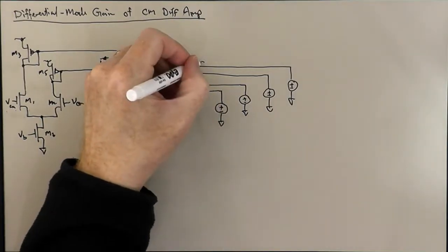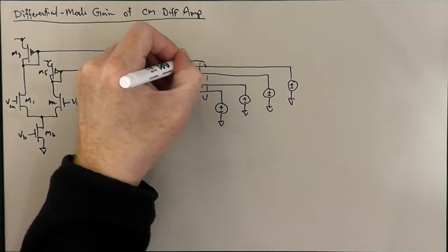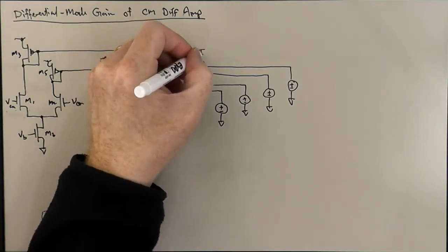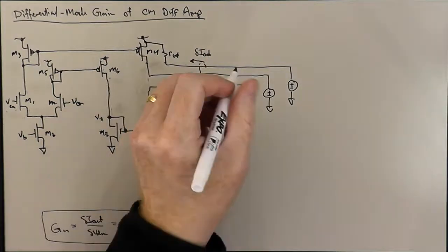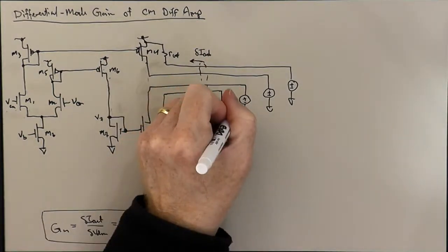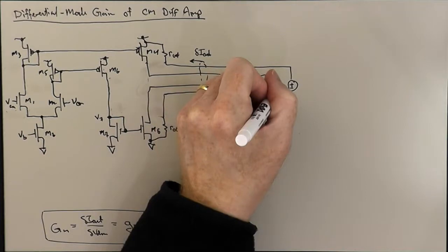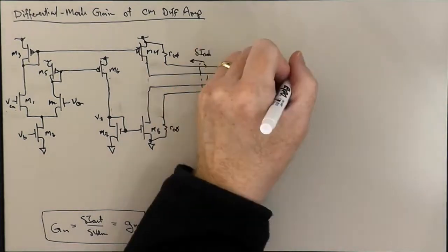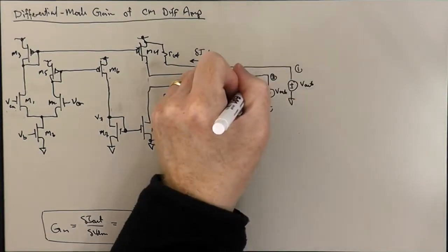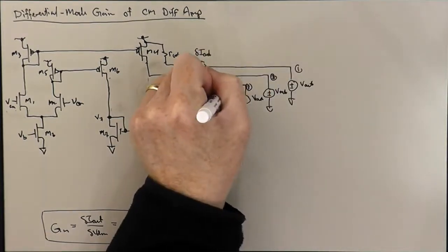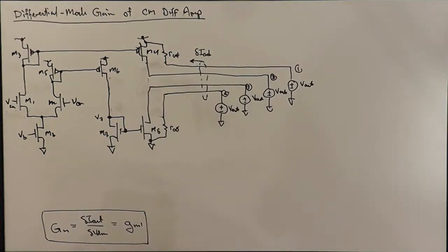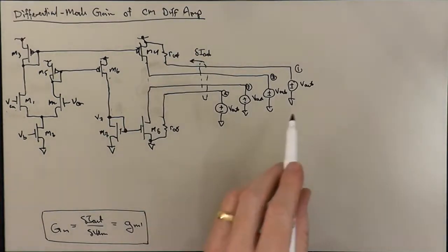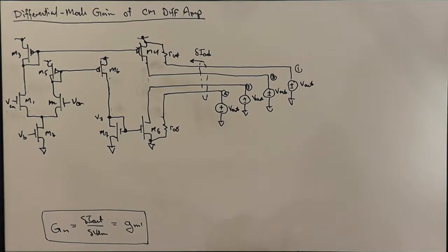We're interested in the total current flowing back through this bundle of 4 wires, delta I out. And so we have V out, V out, V out, V out. We'll call this 1, 2, 3, 4. And we're going to be interested in applying our delta V out to each of these 4 replica sources in turn, and seeing what the components of delta I out are due to each of those.